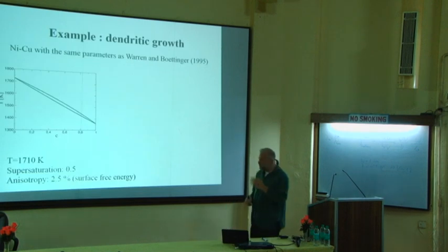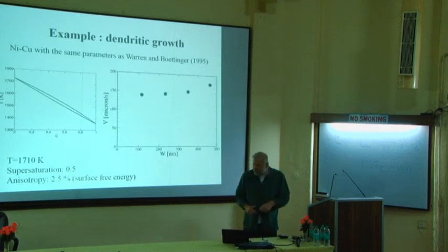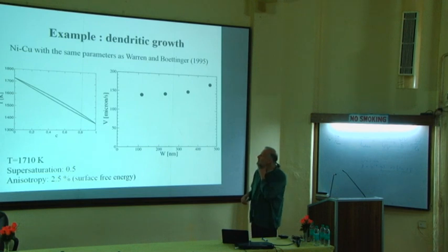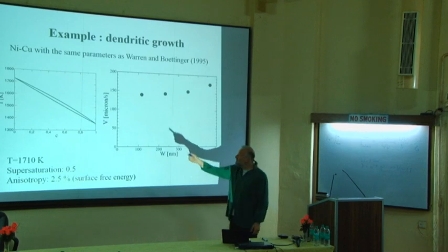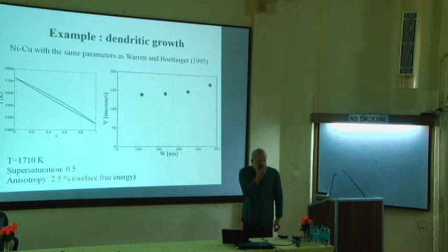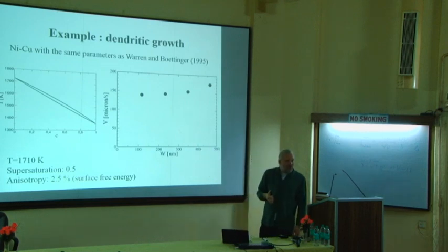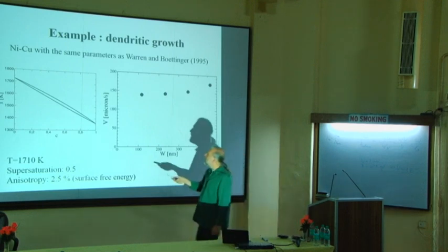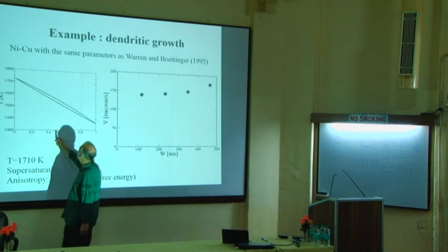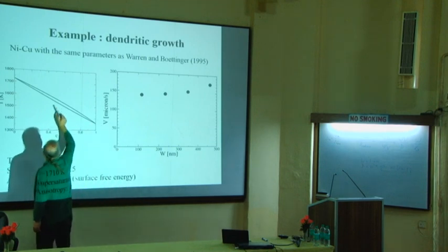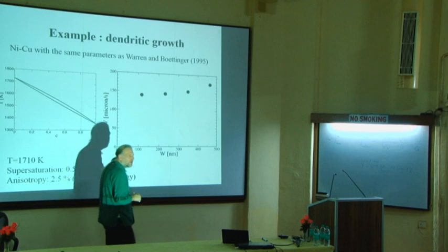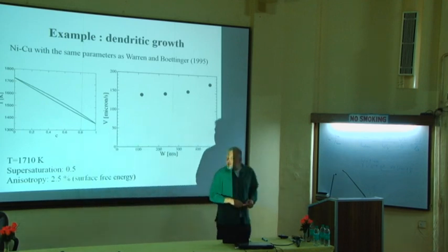Okay, but with this it works, and the demonstration is always the same. So I put up the next graph right away. So here, this is one graph of my 2011 paper. I have taken the nickel-copper phase diagram. So this is a standard lens shape phase diagram. So you can do a regular solution model, or even an ideal solution model for that. And I have gone to exactly c equal 0.5, and I have placed myself right in the middle of the coexistence zone. So this is a well-defined physical system.